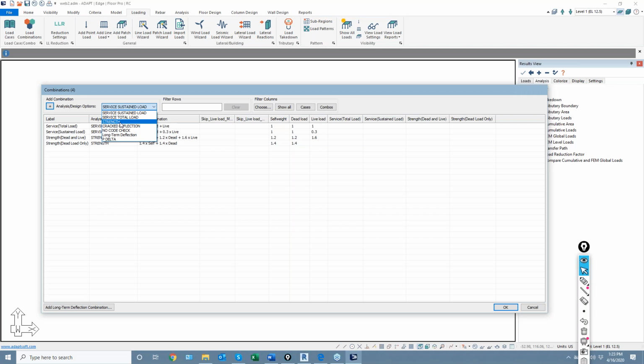Strength would actually be calculated based on the moment demand and any axial demand in a section. So if your ultimate moment is 100 kip feet and the user doesn't enter any base reinforcement, then the program would add enough rebar to meet that demand of 100 kip feet. So that's how strength is handled in terms of reinforcement.